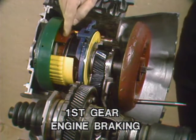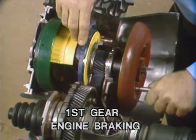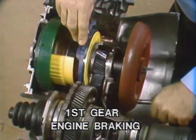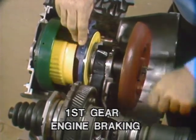Joe has again locked up the direct clutch. With the direct clutch applied, the turbine shaft is locked to the sun gear, and there is no freewheeling either way. The direct clutch is applied for first gear only in the manual low range 1.